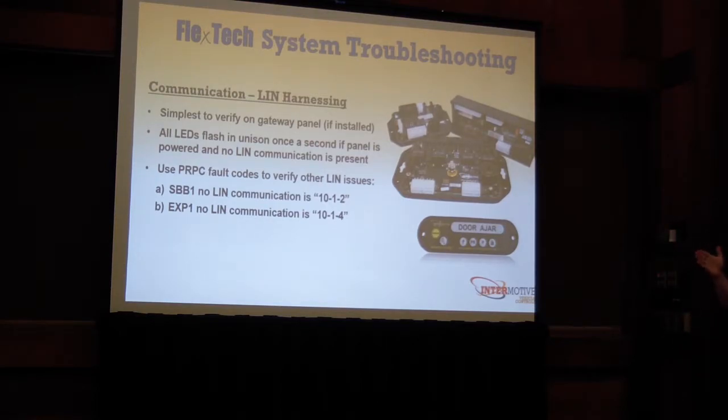After a full fault code is flashed out, that status LED, the amber LED, is going to flash again to tell you what diagnostic page you're on. So that is going to mark the beginning and also the end of a fault code, right? So that's how you can tell what fault code is being flashed out. Makes it a little easier to count those flashes on the fault LED.